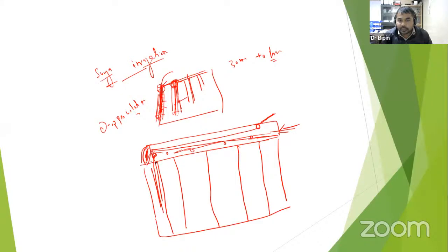When he knows that this field is irrigated, he will pull this wire, and then the blocker will come up to this position. Now water will start to accumulate on this side, then again it will rise, and through this opener it will start to irrigate this field. So again he will pull, then again it will come to this side, while water is flowing continuously from this side, and here it will again rise and come through this outlet.